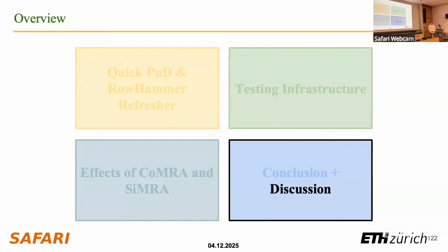So in the future, if you're going to design your DRAM with the capability of performing these in-DRAM operations, you need to take this into account and somehow have a mitigation, because this would make processing using DRAM basically almost impossible, right? So this is like a warning, or we should be cautious about these kinds of things. But in today's systems, you cannot do that because there is no available chip for that. Good question, though.